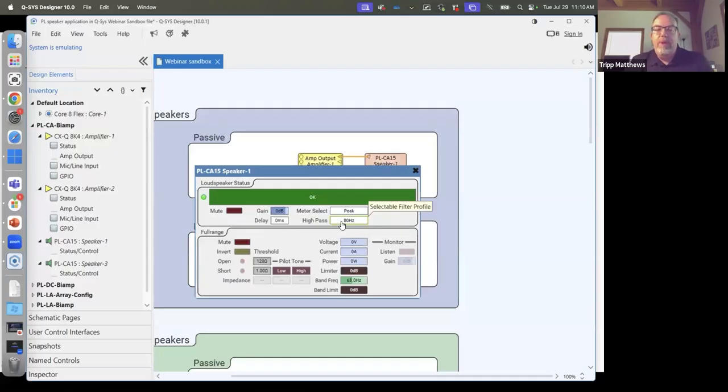You also have a control pin that will allow you to make these changes live if necessary in the event of your system needing some sort of setup change. We do a lot of demoing with full range and then subwoofer, and this keeps that shelving, filtering, and processing to stay in phase with the speaker, so you don't offset phase by putting upstream processing in line with it.